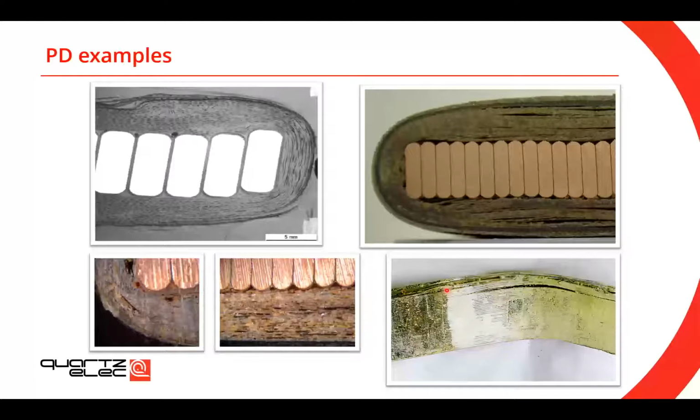And the remaining pictures show you delamination going on in between the insulation layers. And if we come back to one of the slides, we know that partial discharge likes air, because this is where the partial discharge occurs. You can assume that there are a lot of things going on in between these layers.